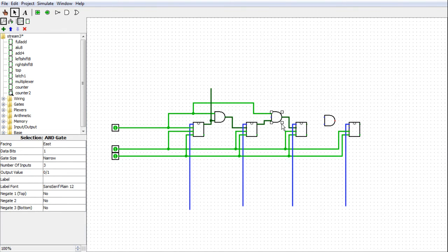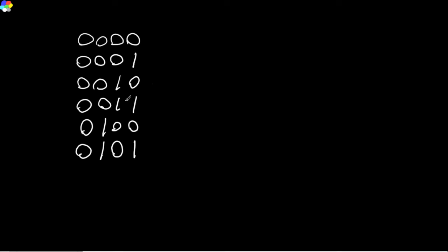Right, because any input, the only time it toggles is if all of the bits before it are already set, right? Because you get a carry, and then toggle. So you have to check if this one and this one are set in order to toggle this one. For this one, it only checks the one before it. This one checks the 2 before it. And this one, if you look, 1, 0. As you can tell, I'm using my mouse now to draw. All right. 0, 1, 1, 1. And then when all of these are set, then this one can toggle.